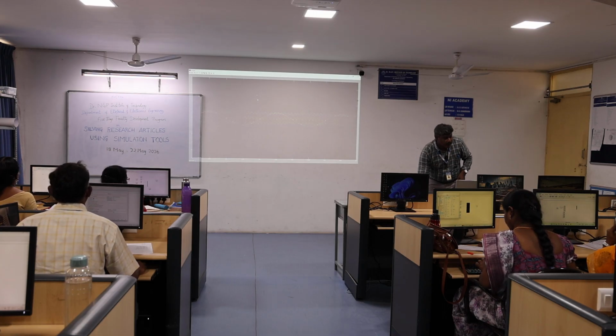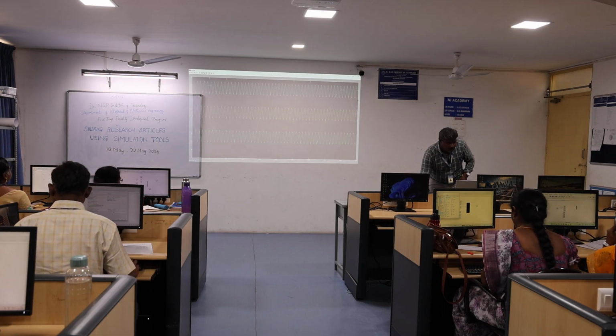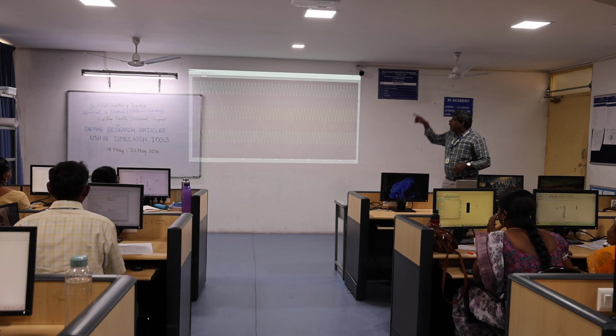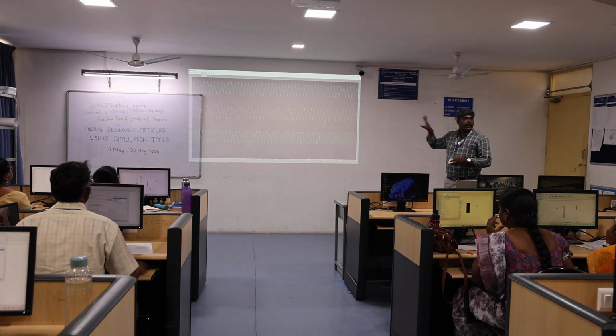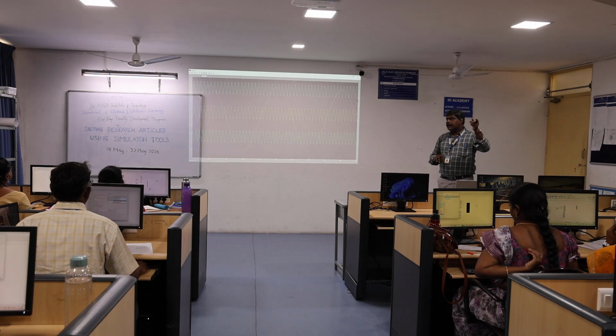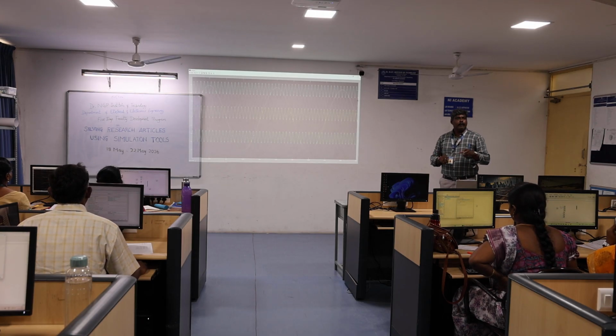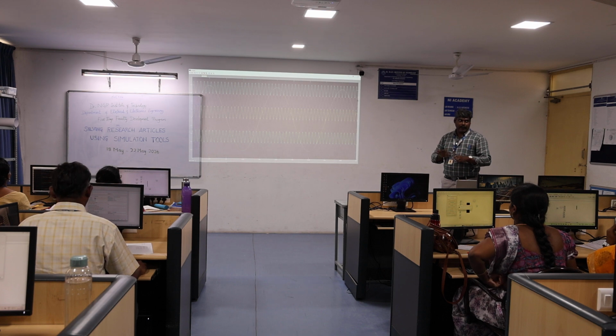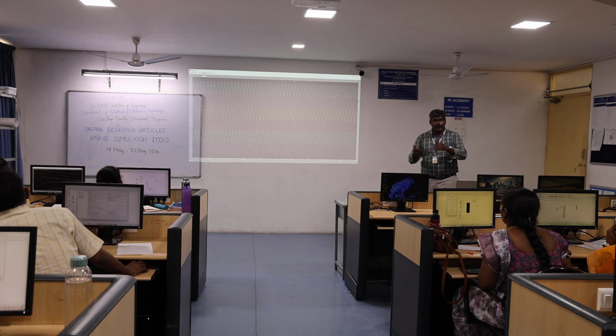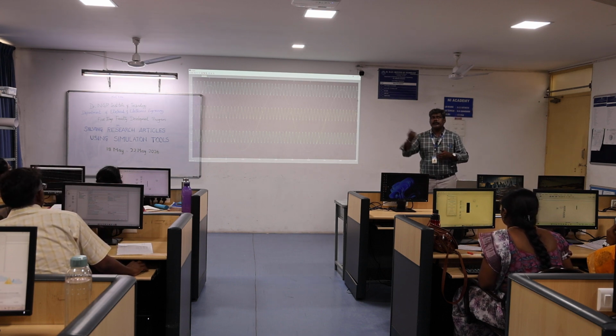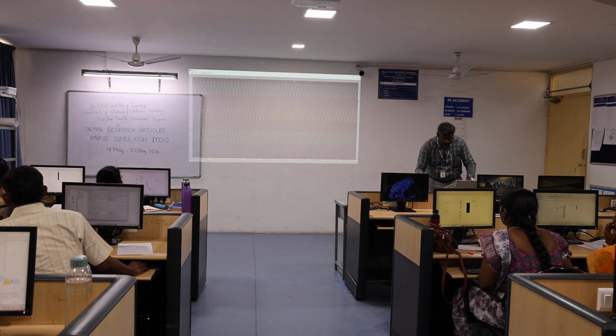So this is the main difference. So now see here, we are generating our triangular, your reference signal and a triangular signal. Okay, so you have to enter the maximum step size and initial step size 1e power minus 7. How we are going to enter that value is based on your switching time period value. Okay, you have to give it below your switching time period value, right?